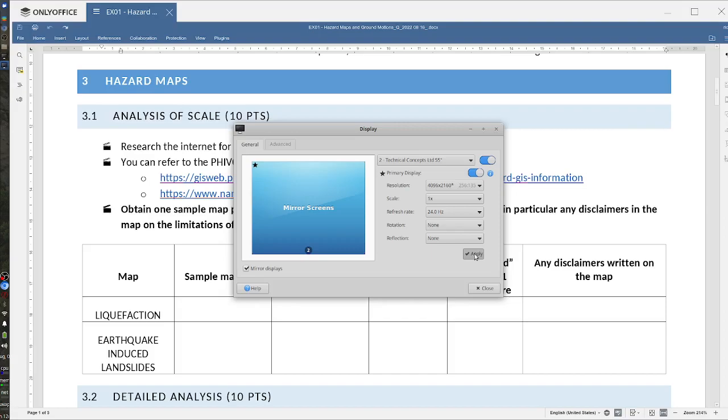Okay? And that won't be easily captured by a 1:50,000 map. Okay? Because this is only showing approximately 50 meters per pixel. Okay? So if your project footprint is less than 10 meters square, okay, and you're expecting a variation of conditions in a scale of a few meters, you can easily miss out or misinterpret the actual hazard. So it's important to do site investigations.